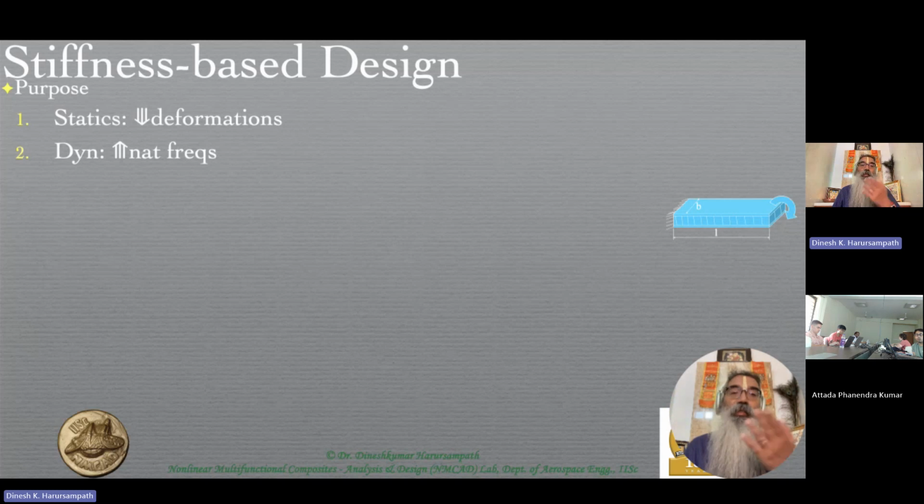One reason for that is this kind of stiffness-based design, taking into account that the natural frequencies are designed in such a way that they are well beyond the typical dynamic loading frequencies. Because especially in helicopters, we know the RPM at which the rotor blades are going to rotate, both for the main rotor and the tail rotor, depending upon the aerodynamic design. And therefore, multiples of that frequency are the loading frequencies